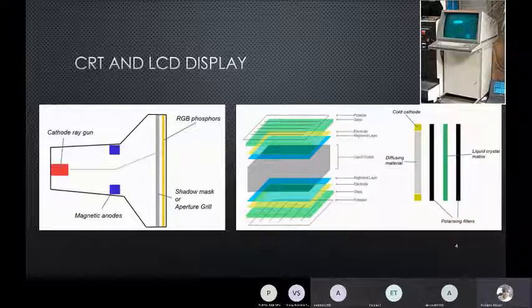In case of LCD display, mostly there is a backlight and it illuminates a set of liquid crystals, and there is a polarizer in front of them, and by tuning the voltage difference, we can create different shades of gray or different shades of light through the LCD. So the LCD itself doesn't emit light, rather the backlight is polarized through the liquid crystals, and that creates the display.